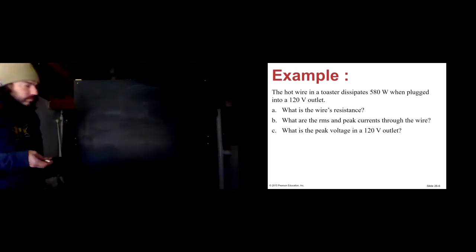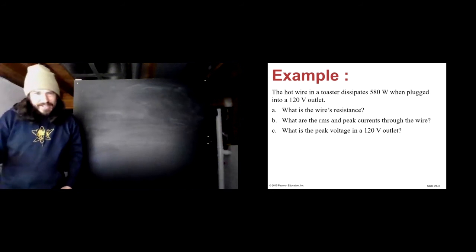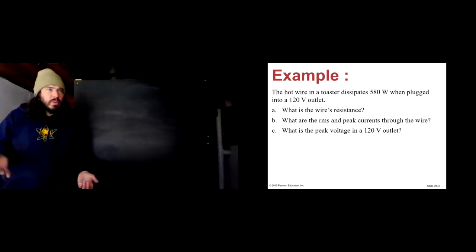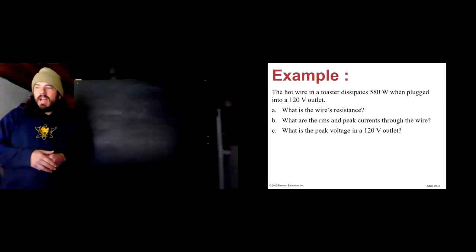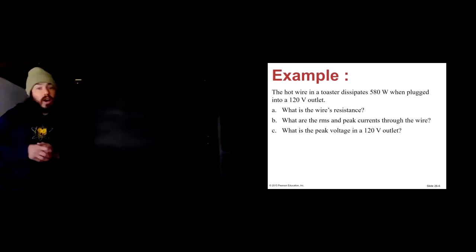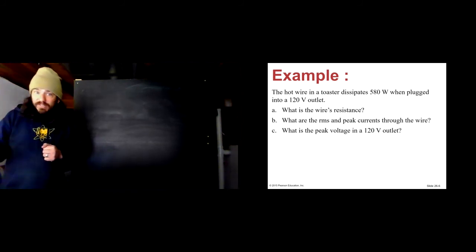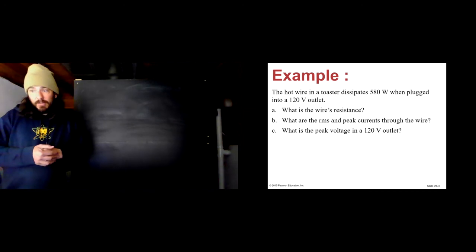Now, let's be clear here. This 580 watts is not an RMS value. The power is always positive, so we don't have to worry about an RMS value. It's really an average over some period of time. When plugged into a 120 volt outlet, the 120 volts there, since I did not specify, we must assume is an RMS value. And so it says, what is the wire's resistance?